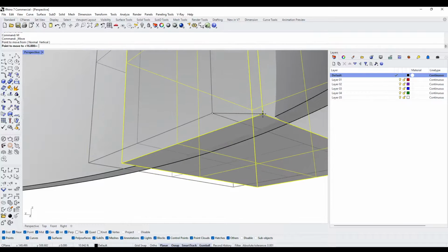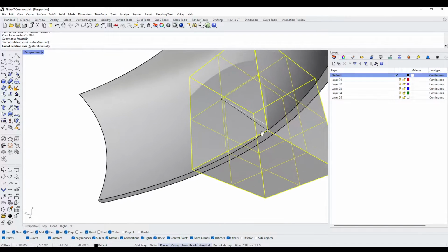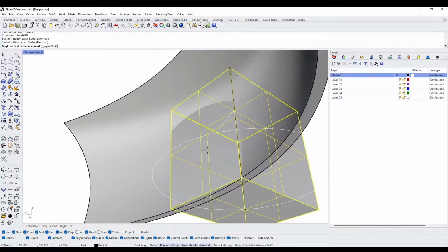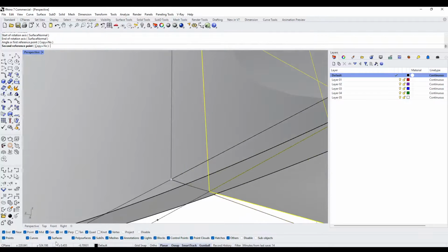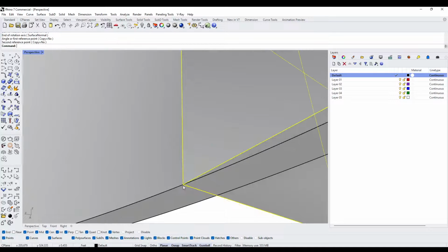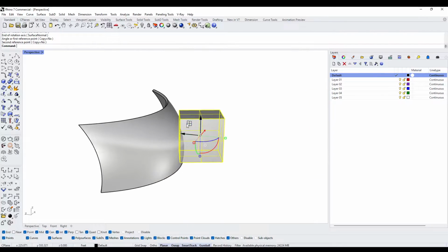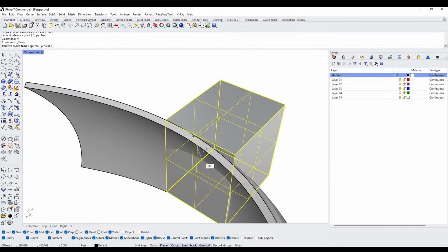And I'll actually be moving this to this and then rotating it from this point and that point to match and meet the wall. So we'll go to rotate, 3D, creating the hinge point between the bottom, top, and this one. And here we can now turn off nearest and use the intersecting point here. Now we can take that and move using nearest, which is okay this time.